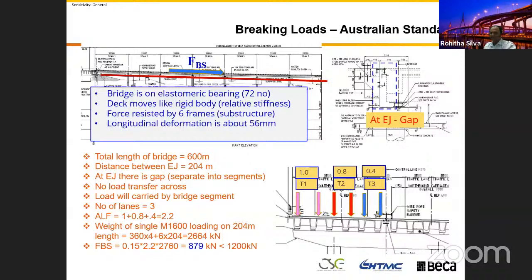Because of that, you got braking, but they are in both directions, acceleration and deceleration in vectors. So if you got a force in the same direction, you double up. No, we don't do that, right? We don't design the bridge like that. The code says you don't want to do that, just consider the one side. That's why I have this loading on the one side, the same example.